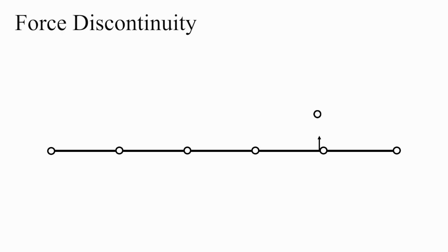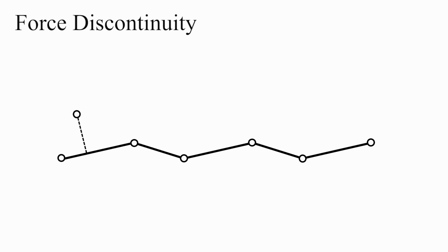segment. While this approach works fine for collinear segments, it leads to force discontinuities in the general case, as demonstrated in this example. Contact force directions change abruptly as the vertex traverses different segments, resulting in force discontinuity. To address this problem, IPC relies on a superposition of smoothly clamped contributions from a set of active primitives, as indicated by coloring.